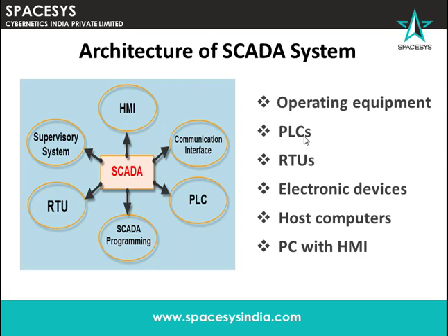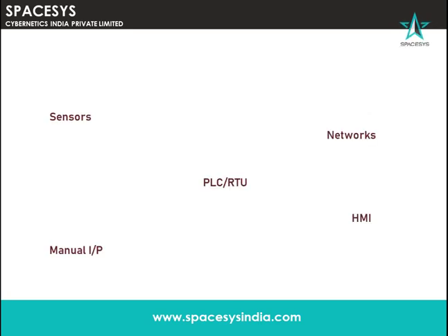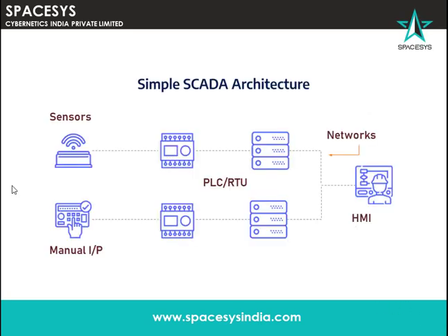For example, in an industrial plant, there are many field instruments used like motors, sensors, actuators, valves, pumps, controllers, drives, etc. In that, the input devices gather the inputs and send the data to these control level equipments or devices. So the data gets processed here, and the processed data is then displayed and monitored through the SCADA system.